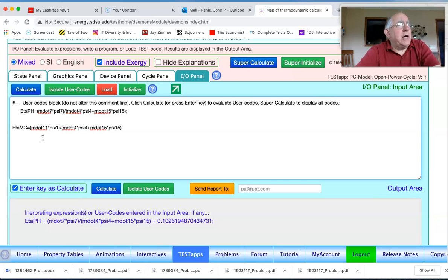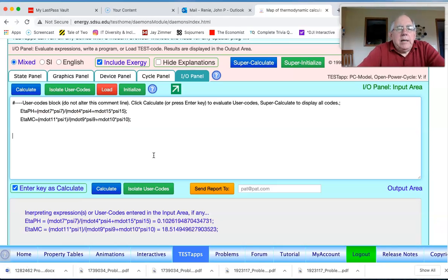That's the exergy coming out of that mixing chamber. And that's due to mass flow at 9 with its exergy and mass flow at 10 and its exergy. So in this case, the denominator is the two streams of exergy coming in. And hopefully we would like all of that exergy to be picked up by the outgoing stream 11. And what we see under this particular case, I made a mistake, and this psi 1 should actually be psi 11.